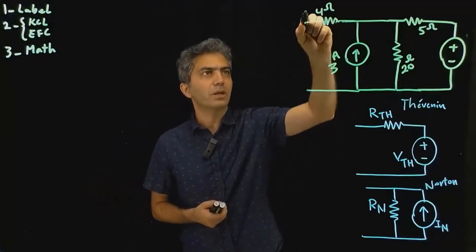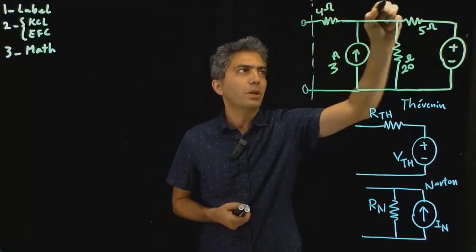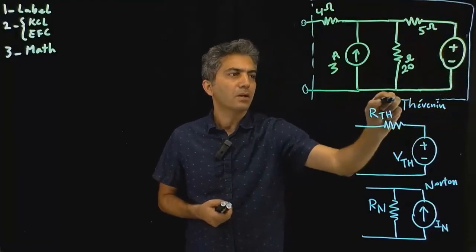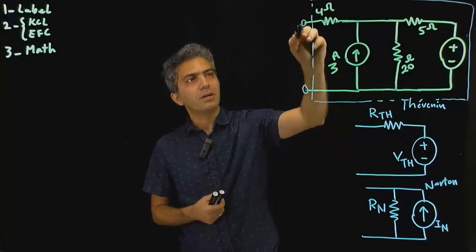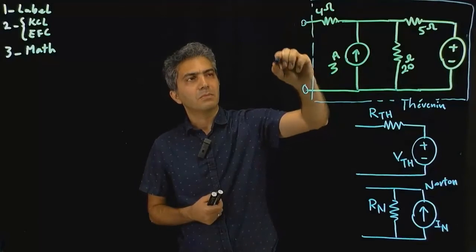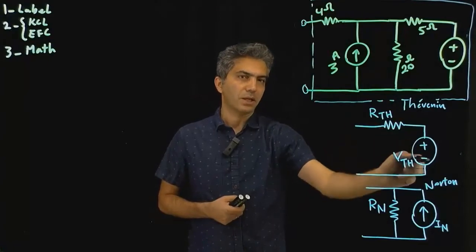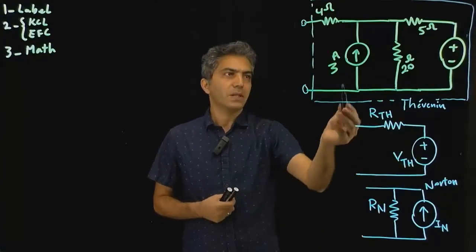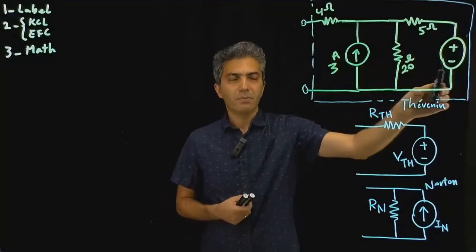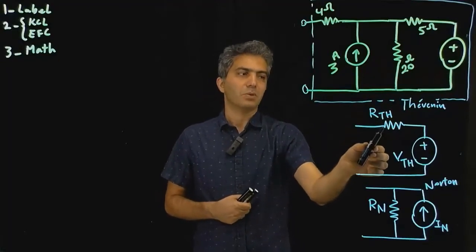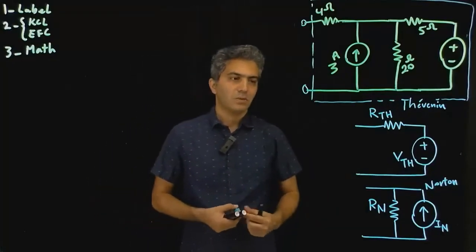So what are we doing here? We're basically saying we take these two terminals for the circuit, we put a box around the circuit, and our claim is that I can represent the current-voltage behavior of these two terminals with a circuit that looks either like this or that. And obviously, the motivation here is that instead of dealing with, in this specific case, 1, 2, 3, 4, 5 components, now I only need to be dealing with 2 components in each one of these 2 cases, which obviously reduces the complexity to a large extent.